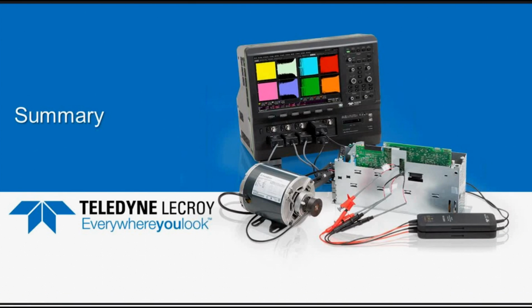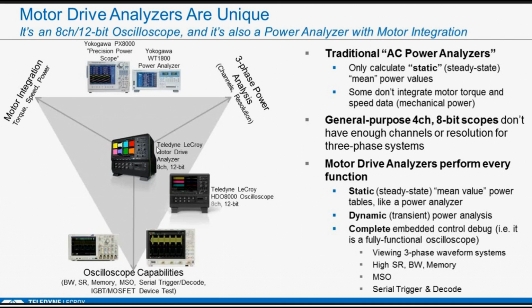Okay, quick summary, then we'll give you some resources, and then we'll take your questions. So we presented this earlier. Now you have a little more context around it. You have power analyzers. Good ones integrate both 3-phase and motor and give you complete motor mechanical power in doing so. Then you have scopes. And scopes are really on the complete opposite end of the spectrum. They're used for control debug. They work great, but they're a very limited tool.